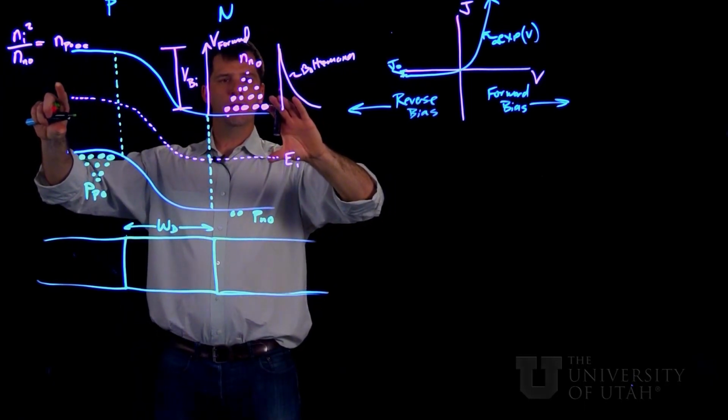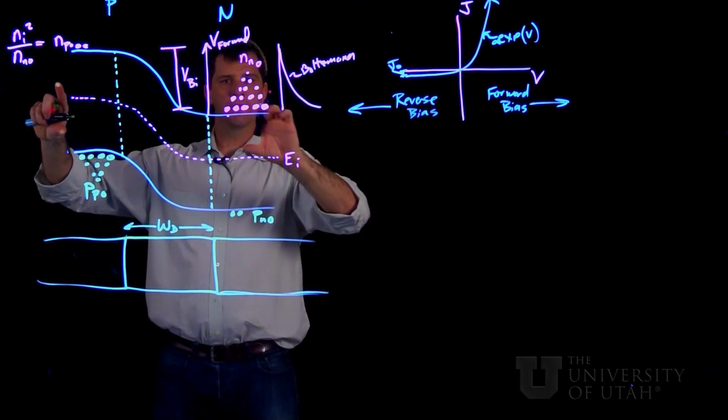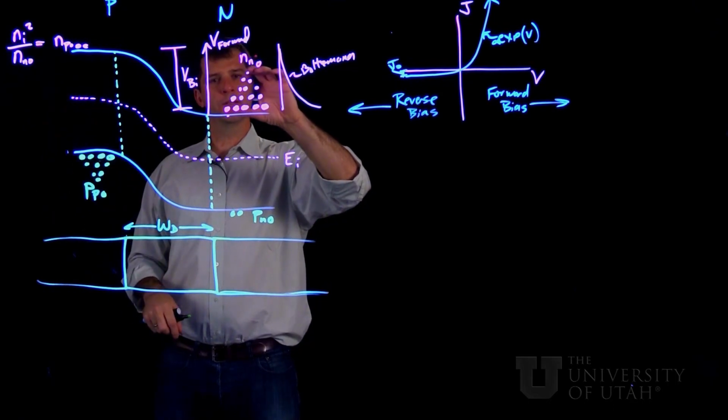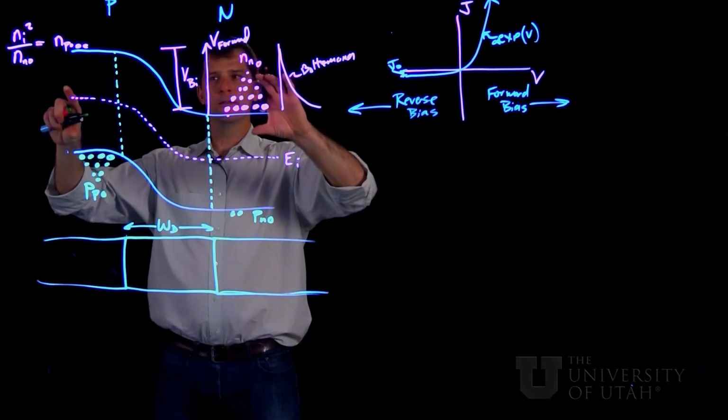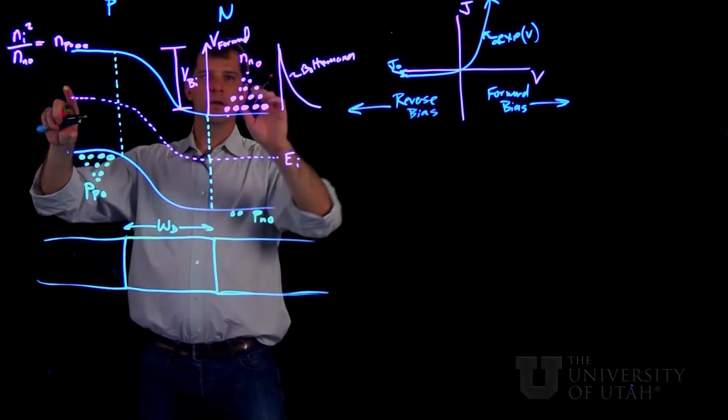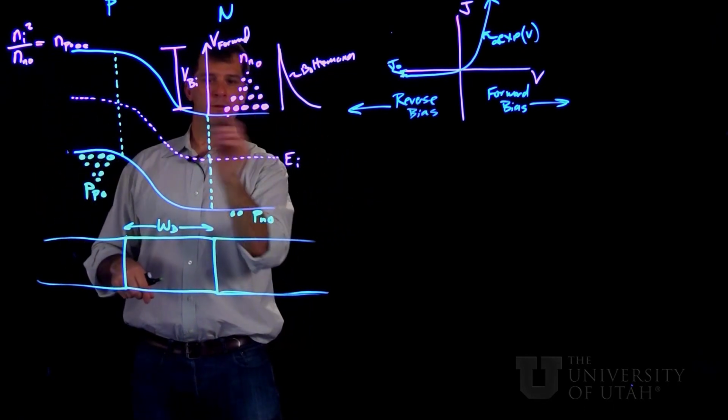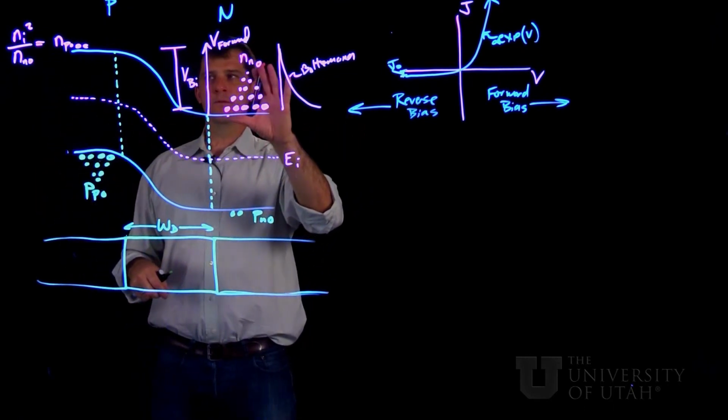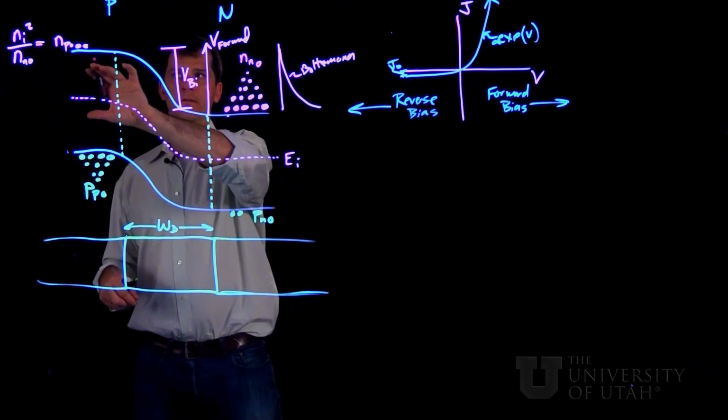So when it moves this band up, it'll do one primary thing. It sort of lifts this large concentration of electrons up in energy so that more of them, as they're diffusing around randomly, left and right, more of them will eventually diffuse across to the other side.